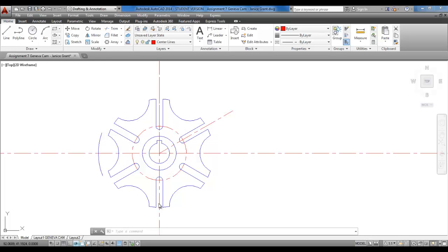So I drew a center line from the center out here along that line, and then I erased the construction line. Now I can select that line, and as long as I keep my line straight to the tracking vector there, that's 30, because I have polar tracking on that 5th icon, I can go ahead and pull this out to where it belongs, somewhere around here, and then I can use it.